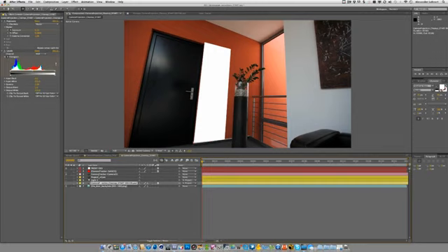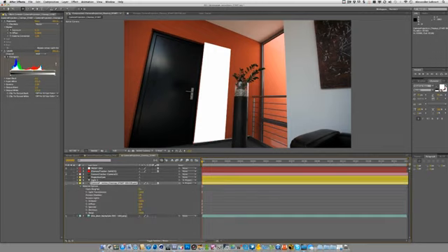Okay, so as we adjusted that, we need to adjust the material settings in our clean plate as well. And for that, we just make sure that we got the cast shadows on, as well as the light transmission set up to 100%, so that each portion of the light is coming through this and gets transmitted onto our proxy geometry.